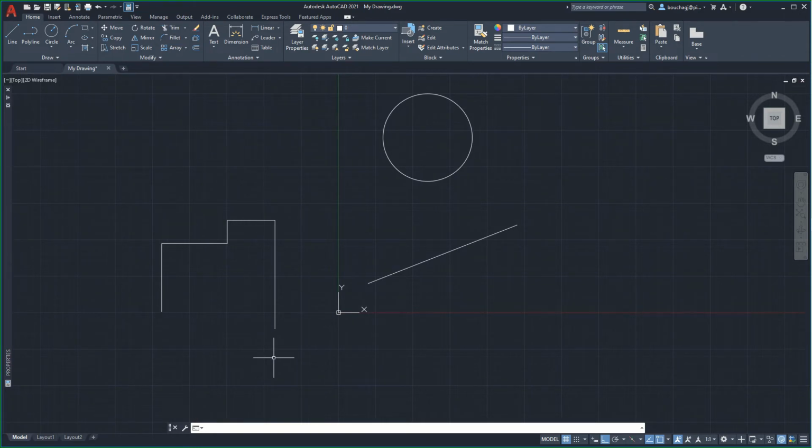There is a distinct difference between the behavior of lines and polylines. Enter the line command, and above the recently created polyline, choose points in model space and create a series of lines similar to the shape of the nearby polyline. Hit the Escape key one time to exit the command and save your drawing.